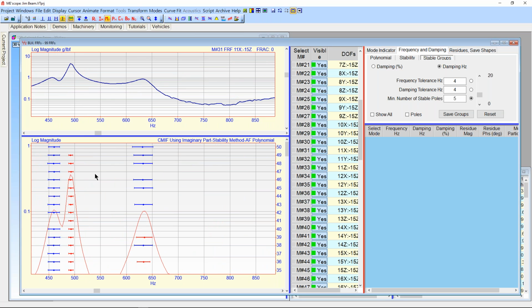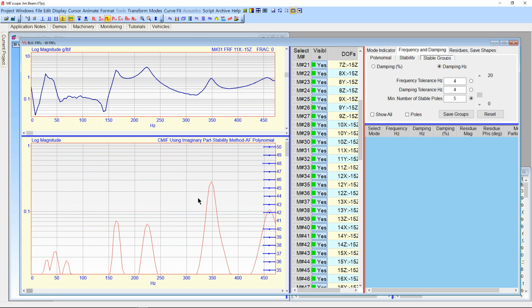that what it did, and over here, it went in and it said, curve fit this data with, well, down here, 1 mode, 2 modes, 3 modes, 4 modes, all the way up to 50 modes. So the curve fitter ran 50 times with a different number of modes in it. And then all the answers are plotted out here. The width of the little bar is the damping estimate, and the little dot in the middle is the frequency estimate. So this curve fitter went through, and then they were all laid on the diagram here, so I can see where the curve fitter got some consistent results.